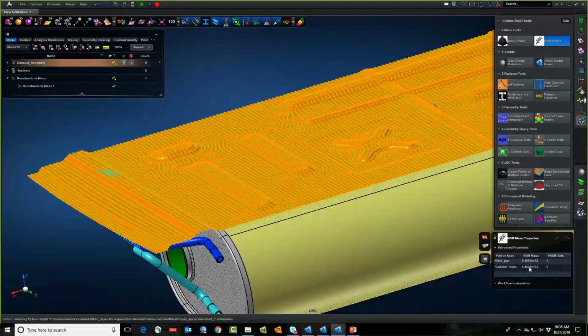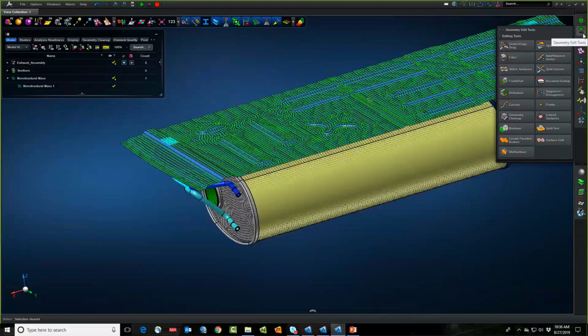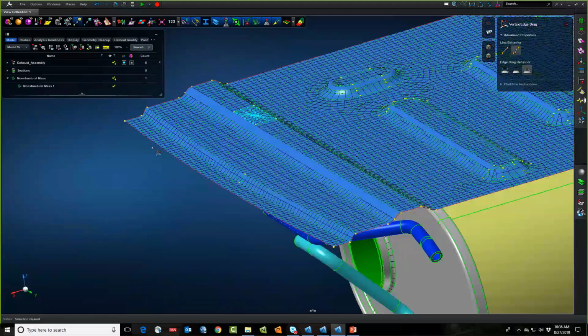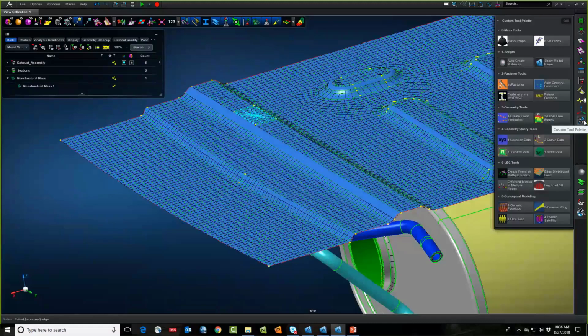And it's showing me that it's about 847, all right? So I'll just accept that value and close that out. The neat thing about this is, like everything else in Apex, this is generative. So if I come in and change the size of the floor panel, the non-structural mass is going to update automatically. It was 847, all right, for the original structure.